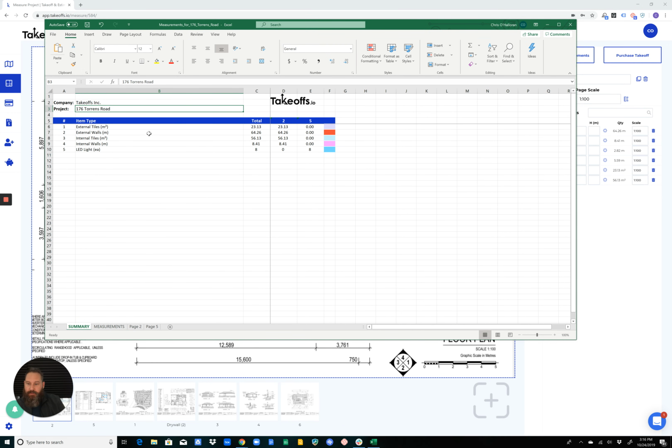The summary tab is going to give you a view of each page that has a markup, and it's going to set this up so that if we have, say, LED lighting across multiple pages, that'll be tallied up. So you'll see that page 2 doesn't have any LED lighting, but page 5 does. So if we had multiple pages of lighting, this will tally that up across all those pages, which is a really good way of seeing quantities if you're working on multiple floors.